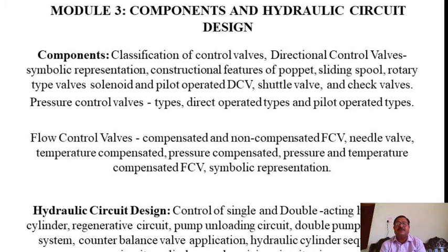And then shuttle valves. Here the direction control is done by means of a type of shuttle which is incorporated in the valve. And then check valves. Here only one side of the flow is allowed, and the other side is not allowed.